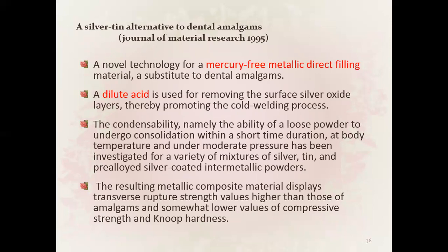The condensability, namely the ability of a loose powder to undergo consolidation within a short time duration at body temperature and under moderate pressure, has been investigated for a variety of mixtures of silver, tin, and pre-alloyed silver-coated intermetallic powders. The resulting metallic composite materials display transverse rupture strength values higher than those of amalgams and somewhat lower values of compressive strength and hardness.